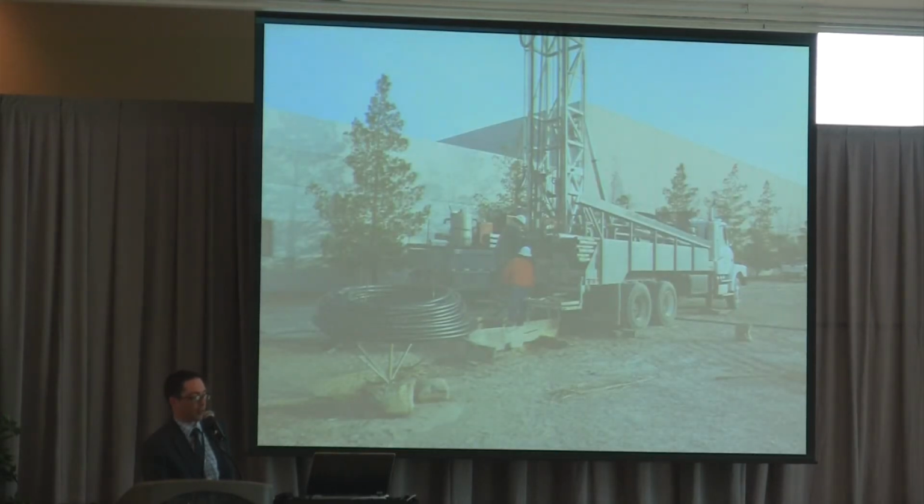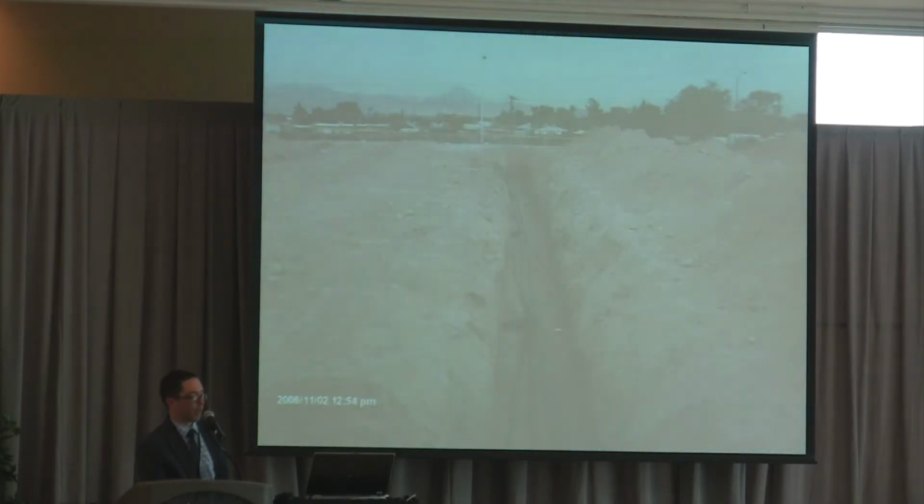I'll show you just a couple pictures for people that aren't familiar with the technology. Here you can see a typical drilling rig installing a geothermal ground loop. This is the loop here, this black pipe, high density polyethylene, and a large commercial system. My home has 2 of those loops in the front yard. A large commercial system might have hundreds. There are also other ways to connect to the ground loop using ponds, water wells, lots of other options that I won't get into in detail here. This is the most common. And then multiple boreholes here are shown headed together in a trench prior to being buried.